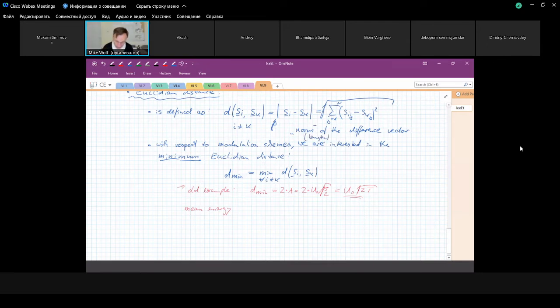Okay. So in the mean energy, in this example, it doesn't matter because all the signals have the same energy. Then we would say the mean energy, let's denote this as ES, is equal to E1 plus E2 plus E3 plus E4 divided by 4, but all have the same value. And these energies were u naught squared times T, right? And now we could say this value here can also be expressed as a function of this mean energy.